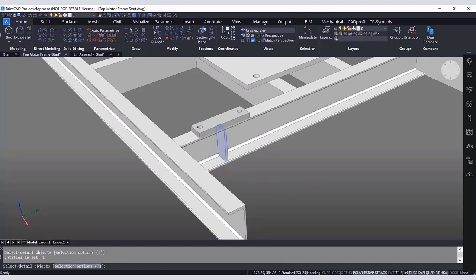Here you can see another detail. Like the plate, this rib gives the beam extra strength in these mounting positions. As you can see here, this rib is snapping onto the channel of this beam, but it still has some movement allowed, meaning that no face is forcing it into a specific placement along the beam.